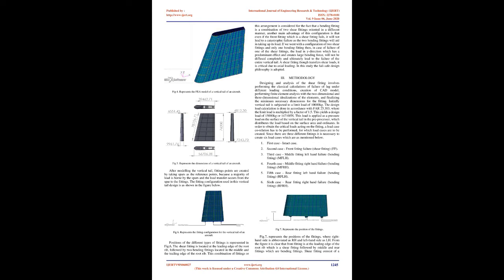ASME BTH, the American Society of Mechanical Engineers method, considers most of the failure modes above, and uses simplified equations with correction factors based on empirical data to determine more accurate allowable loads. This method is simpler than the Air Force method, but it only allows for lugs under axial loading and does not account for the interaction between the lug and the pin. 4.